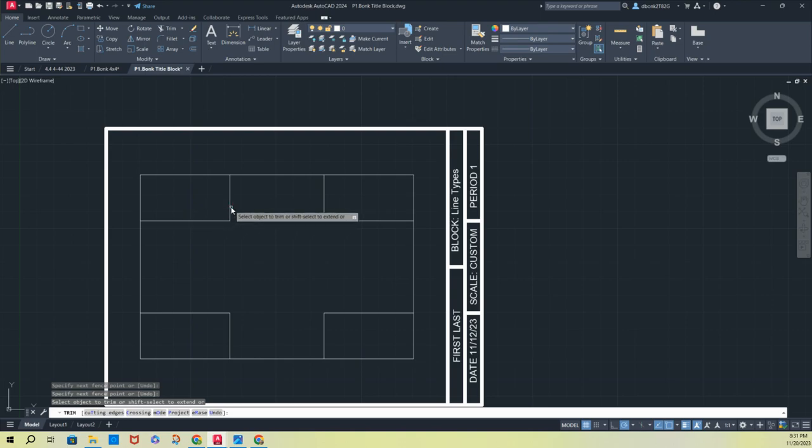So what you do is you select, you just click on the line. Oh, I'm sorry, my trim is still, it's trying to delete them. If I hit the escape key, I can select these 2 lines and then type the letters join. And it's going to join those 2 up. So it's going to offset them together. You'll see this is going to make your life easier in a minute. Click these 2 and join. Click, click, join.